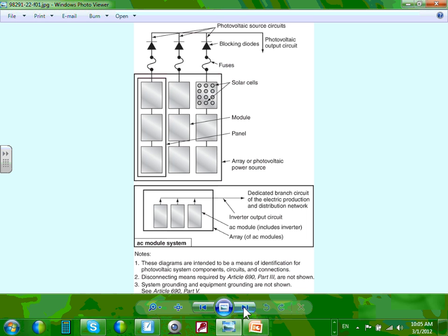Your inverters, guys, we talked about the inverters can go from 2 kW to 500 kW. I don't know if we missed any of these things. Ground fault protection, we talked about this one. Chris, did we miss anything? Okay, I have inverter ground fault label, bipolar system disconnect labels. There's a lot of labels that you have to apply, labeling the disconnect as solar photovoltaic disconnect and so forth. Combiner boxes and so forth. I think we covered most of the stuff that I want to cover anyway.